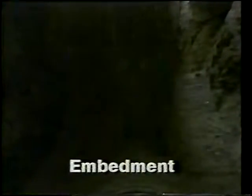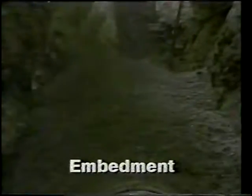Placing and compacting the embedment soil in accordance with specifications is the most important step. The type of embedment soil and the degree of compaction should be specified in the design.